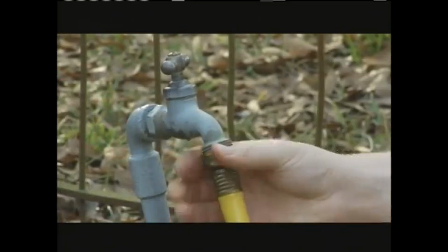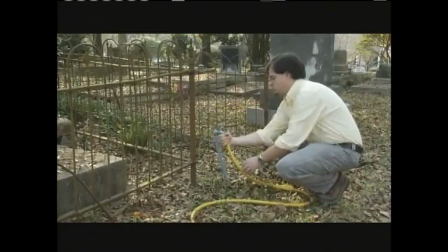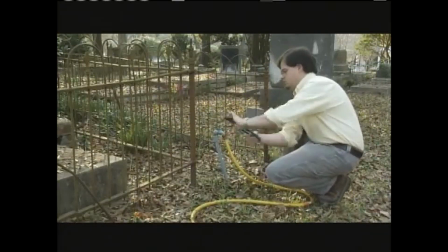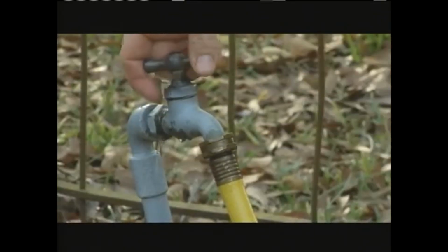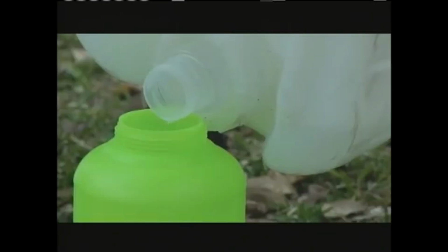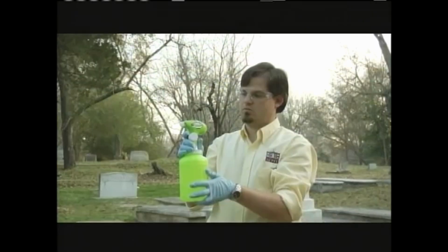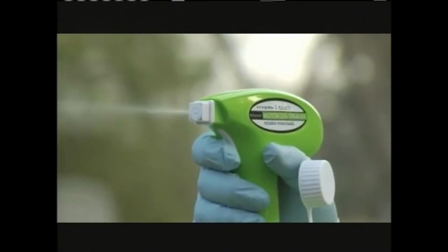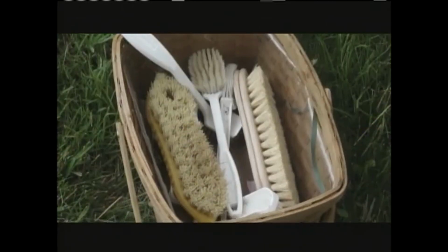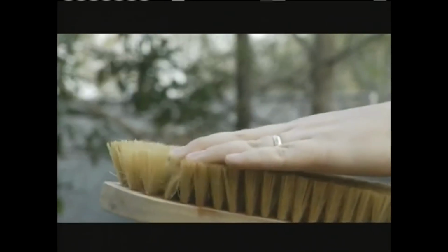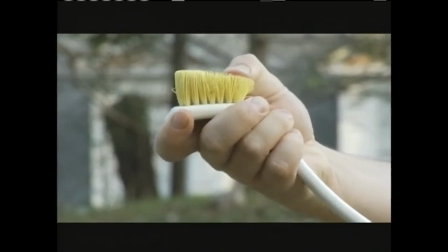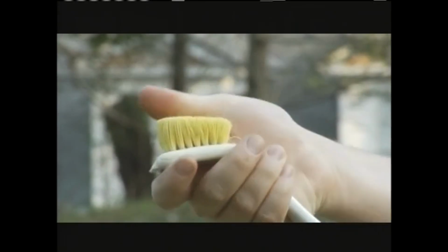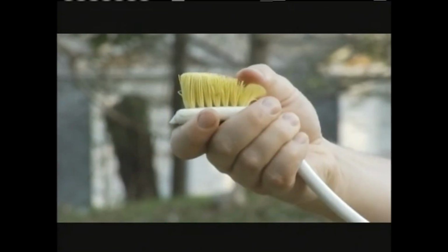Always locate your nearest water supply. It takes a lot of water to properly clean stone. If your cemetery does not have running water, then it is important to bring barreled or bucketed water to the site with you. Also, it is good to have your selected cleaner in a convenient spray bottle. As for the brushes, you always want to use soft bristle, either a natural or a synthetic. The general guideline is that if your brush is safe for cleaning the hood of your car, then it will work well for historic stone.